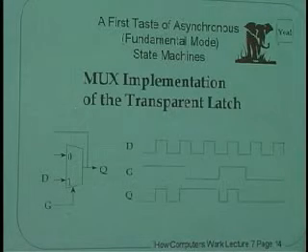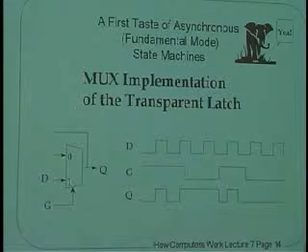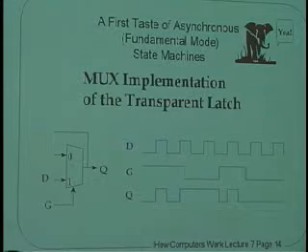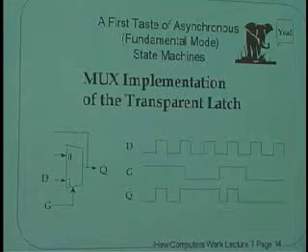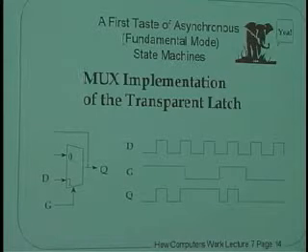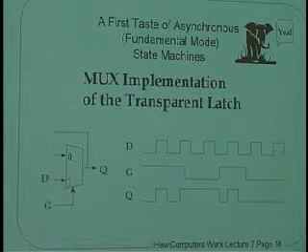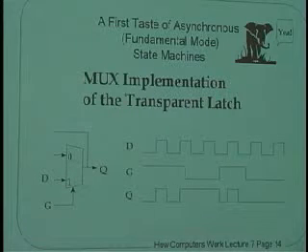Okay. So let's start to build some memory out of this thing. We have in our hands a hazard-free selector. Kind of a cool thing. G can go up and down. We've called it G now. And into the 1 input, I'm going to feed a data input called D. And out of the output of the selector, I'm going to take an output, and I'm going to call it Q. And here's how it works. We're building the memory here. When G is high, when the gate is high, the output Q is going to do what?